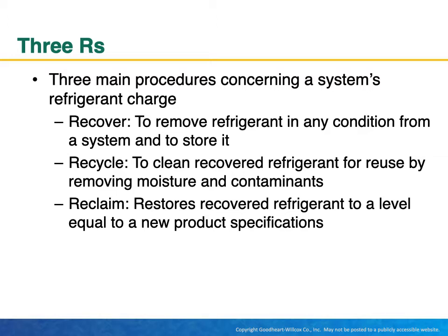The 3Rs. Three main procedures concerning a system's refrigerant charge. Recover: to remove refrigerant in any condition from a system and to store it. Recycle: to clean recovered refrigerant for reuse by removing moisture and contaminants. Reclaim: restores recovered refrigerant to a level equal to new product specifications.